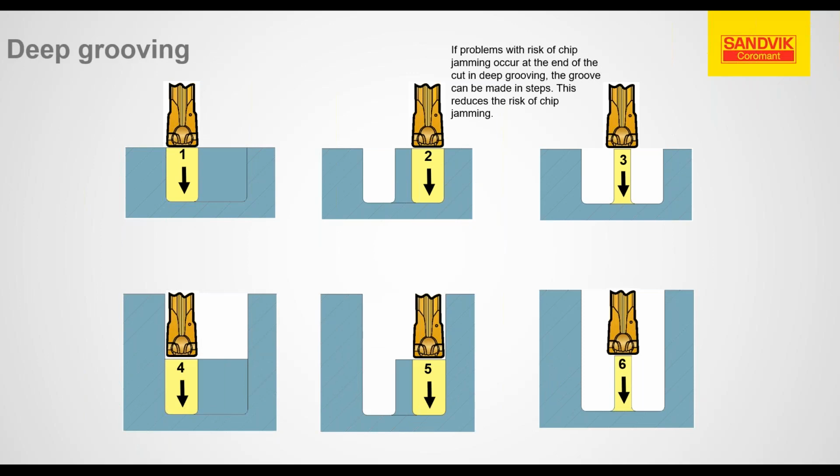For deeper grooves, we can actually alternate where you take a shallower groove, clean the material out, and then actually step down deeper and alternate your way in. This just helps with the chip evacuation so that you're not going too deep and binding up chips into the slot.